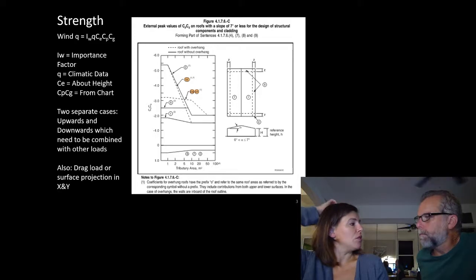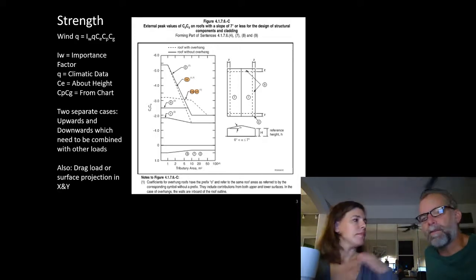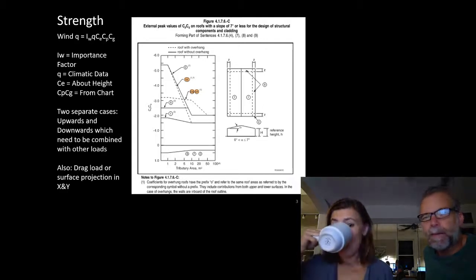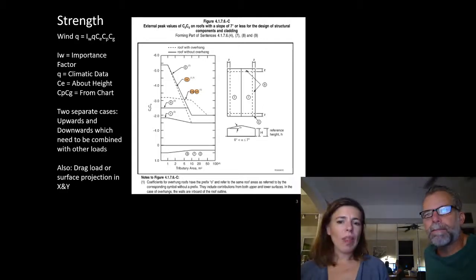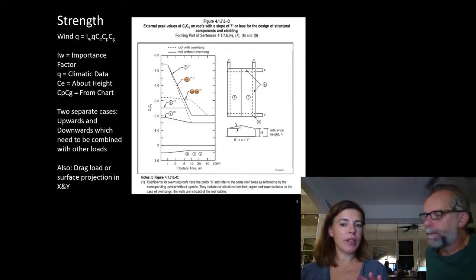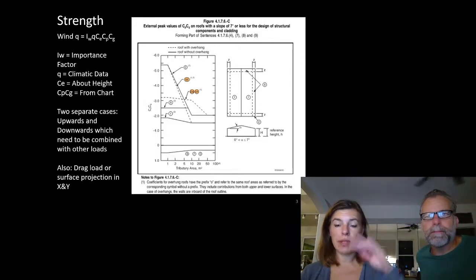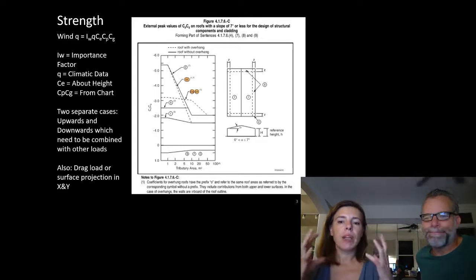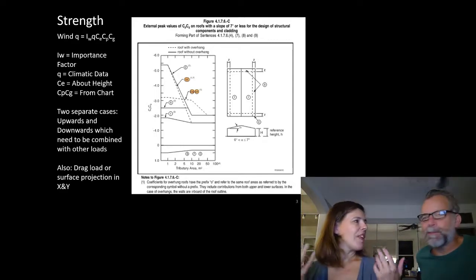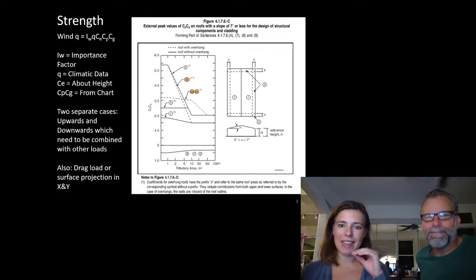Do you follow that? Do you do that too? Yeah, in fact, ASCE 7, which is the American code, has a specific provision for that. Something like 1% of the projected wind load. Yeah, I use about 2% just to be conservative, because I'm not usually applying that with snow load, because snow load is a gravity load, and I'm applying these independently. And of course I'm doing it on fabric structures, which are very smooth. Yeah, so the wind just blows right over it.